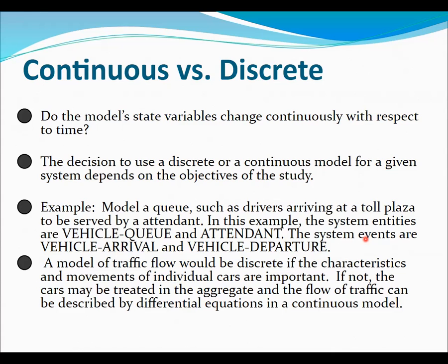Now, do we ever use continuous modeling? Actually, we do. Remember how we model traffic flow versus density? It's the curve that I showed you this morning in the lecture. That's continuous flow modeling. You're treating the whole of traffic as one flow, and you're able to model speed versus density and density versus flow. Those will be your continuous models.